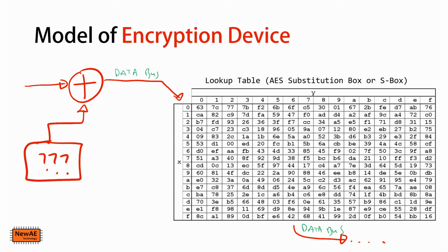So we're going to use this assumption that the number of ones on this data bus here and here is going to be related. So ones on bus is related to a power consumption measurement. And this is something we just assume is true for this particular device.